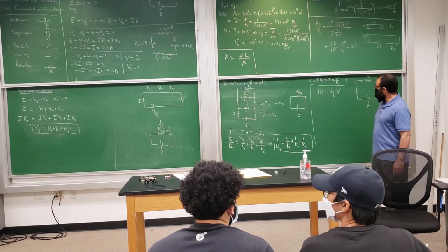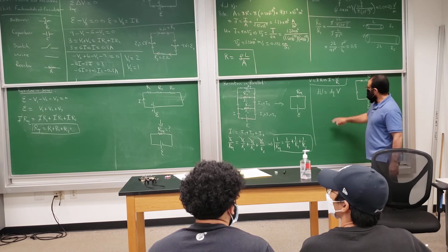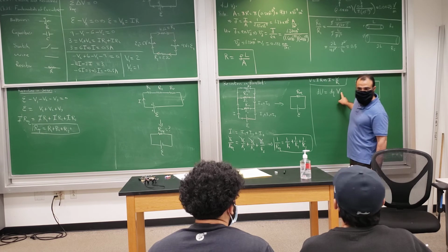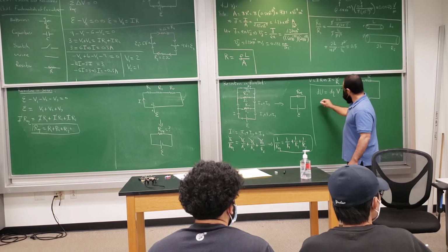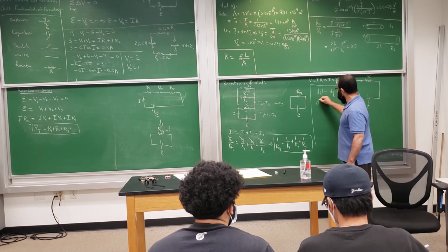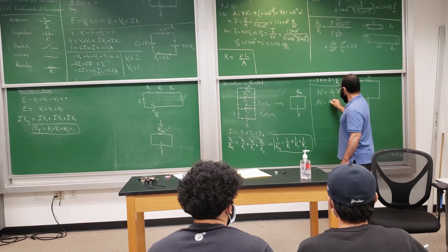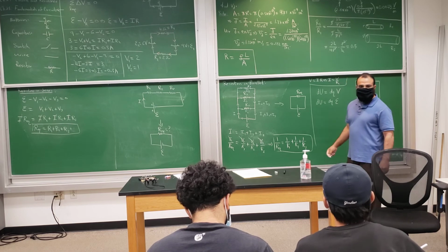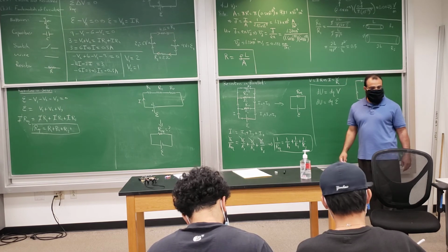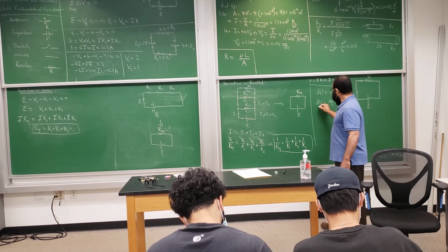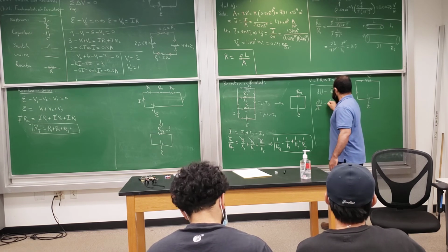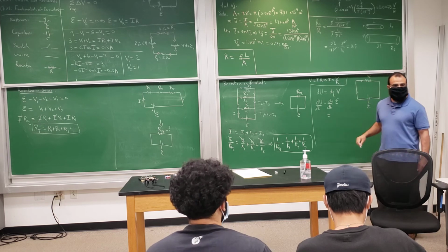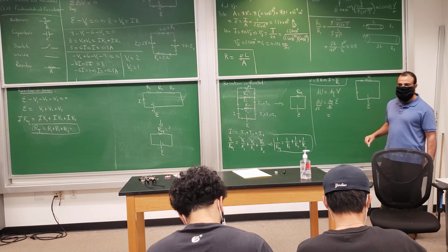So dU. Now, since the voltage here is coming from the battery, this V is really V of the battery, the EMF of the battery. So I'm going to say dU will equal dq times the EMF of the battery. If I divide both sides by dt and take the limit, you would have dU/dt. Well, dq/dt is also known as the current, right? dq/dt is the current.